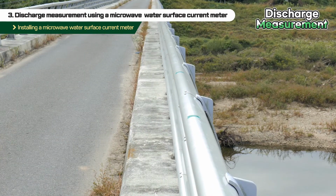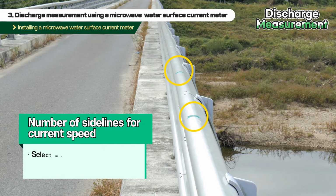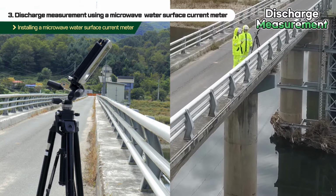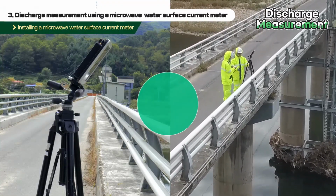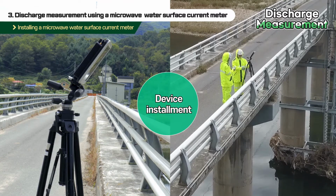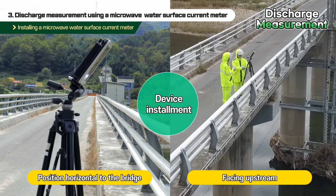The current speed is measured by changing the number of sidelines according to the width of the river. For sidelines, they are selected with more than 20 considering the precision and uncertainty of the measurement, and are deployed according to the width of the river. After checking the number of sidelines by the width of the river, the microwave water surface current meter should be installed. At this time, the current meter should be at least 40 centimeters higher than the railing of the bridge horizontally, and the head should face upstream.